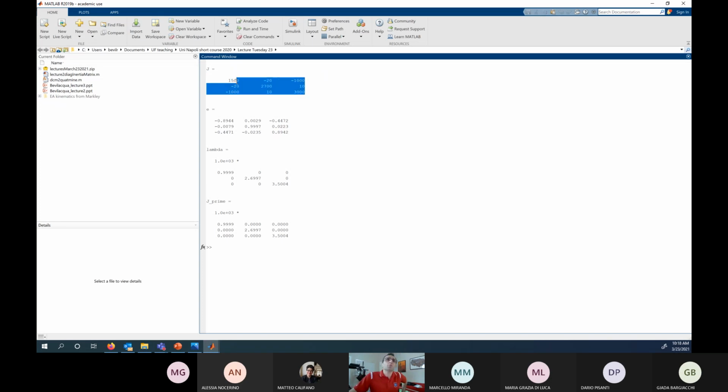So here I have computed, for example, the matrix of inertia with respect to some coordinate axis attached to my spacecraft. Then I compute these three directions, the eigenvectors of this matrix, and this gives me the direction of what we call the principal axes of inertia of my spacecraft. And so with respect to these axes, the moments of inertia collapse to only three values on the diagonal. As you can see, these three values reappear on the diagonal of this matrix, and you have no off-diagonal terms in this new coordinate system.